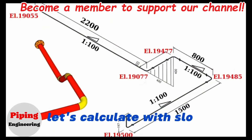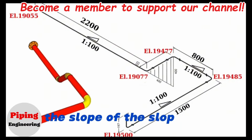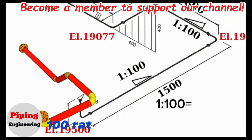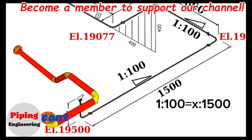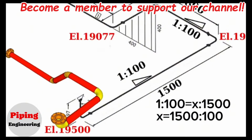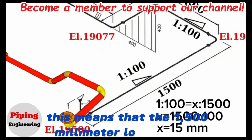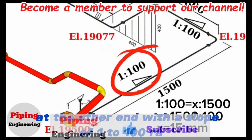Let's calculate with the slope ratio in this example. In this pipe isometric drawing, the slope at a horizontal distance of 1500 is expressed as a ratio of 1 to 100. 1 to 100 ratio equals x to 1500 ratio. Continue: x equals 1500 over 100. Continuing the calculation, we find x equals 15 millimeters. This means that the 1500 millimeter long pipeline falls 15 millimeters down at the other end with a slope of 1 to 100 ratio.